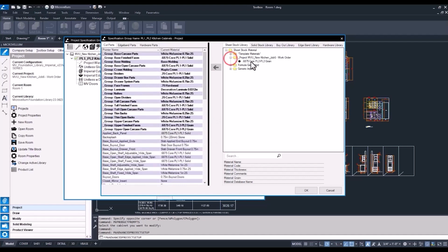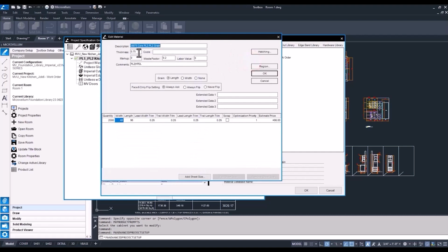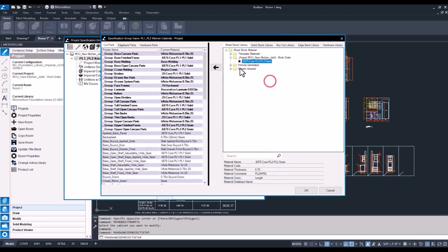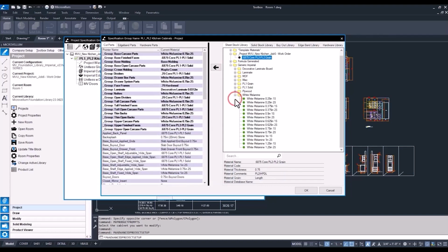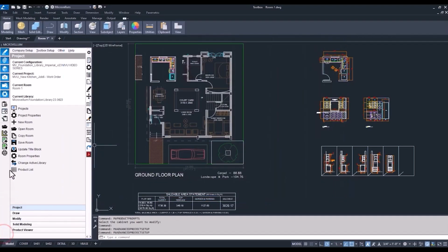And also you want to make sure that your material thickness in Toolbox is matching up with the actual material that's being used for production. Now, trust me, I have some experience dealing with some thickness issues in the shop, and it's not good. There could potentially be a lot of rework. So double check your material thickness. Now, not only in your project, but also at the library level. The stock material that you're using in the shop should have the exact thickness set up inside of Toolbox or inside of your template. We're going to go over 3 different ways that you can create a work order.